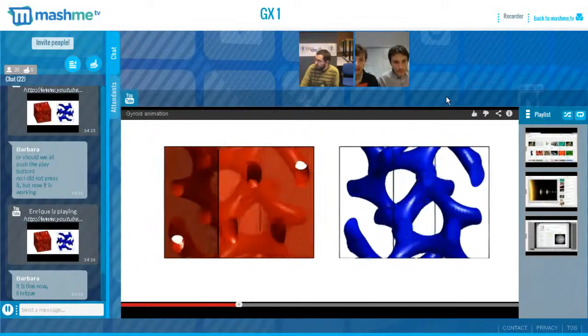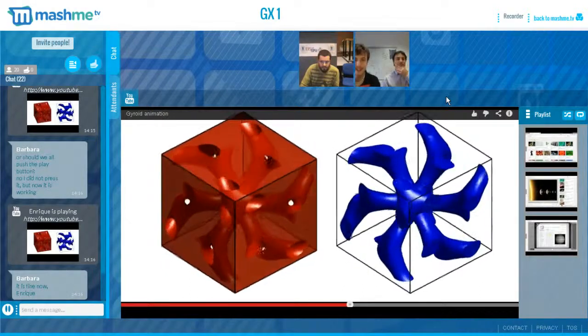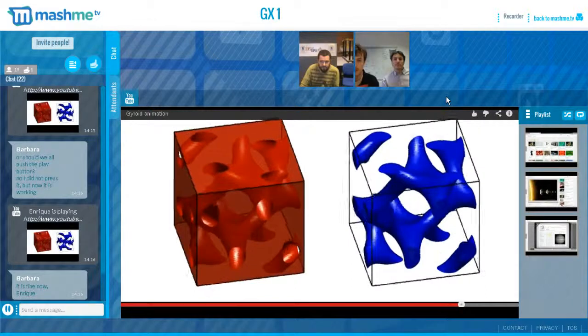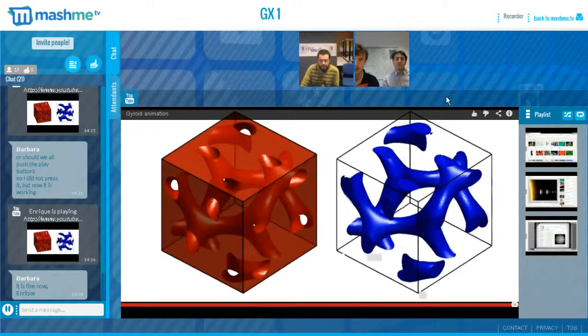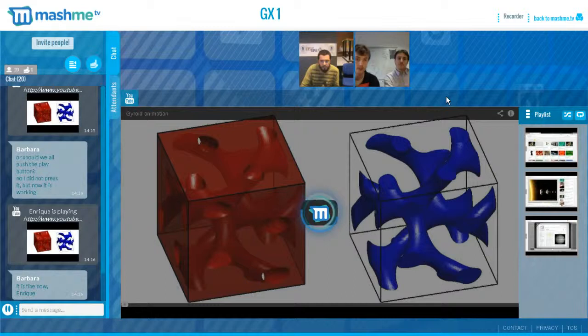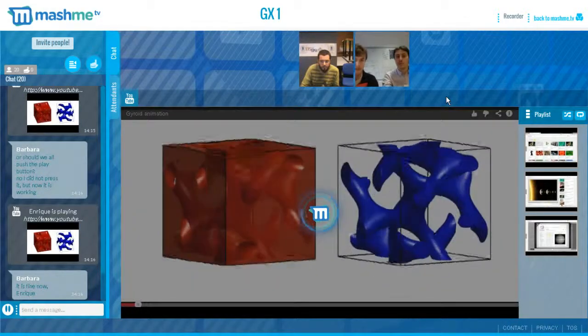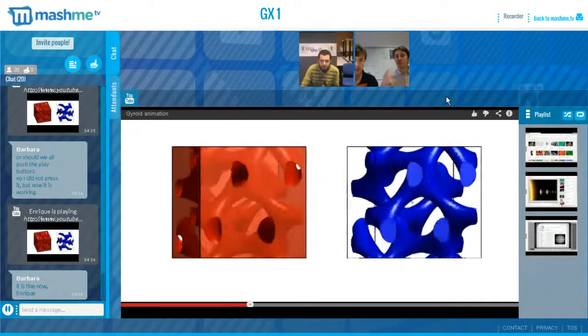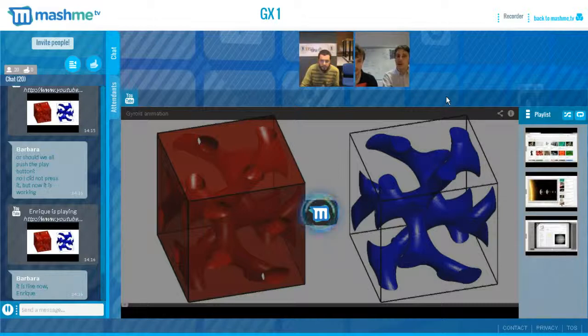So this is a schematic representation of this gyroid structure that we're talking about. We've separated it because it's made up of two different components, which we labeled the red and the blue part of the polymer. We've split this to show you the blue and the red network. And you can see then, if you etch out one of the phases, either the blue or the red, you get left with this porous structure, the remaining one, the one you didn't etch out. And we use that porous structure as our template. And just to be clear, this is a nanostructure because the size of these pores is around 20 nanometers. If you take these unit cells and put them together, you get a three-dimensional object like the prints we are using. And we could go back to the presentation, please.